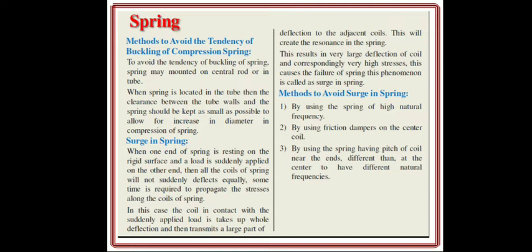What is surge? When one end of the spring is resting on a rigid surface and a load is suddenly applied on the other end, then all the coils of the spring will not suddenly deflect equally. Some time is required to propagate the stresses along the coil of the spring. In this case, the coil in contact with the suddenly applied load takes up the whole deflection and then transmits a large part of the deflection to the adjacent coil, and this will create resonance in the spring.